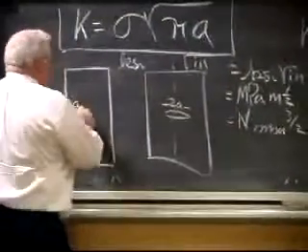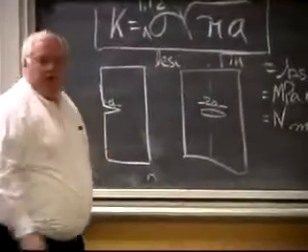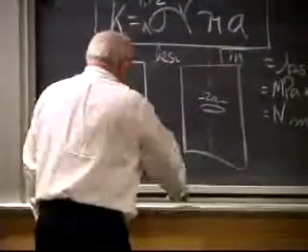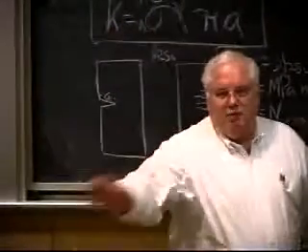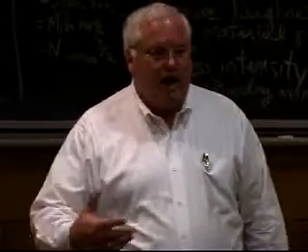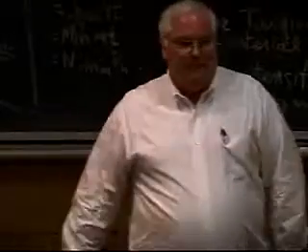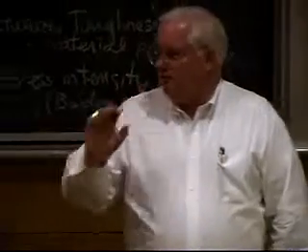times the square root of pi a. If you're talking about a pure edge crack in plane strain, there's actually a factor of 1.12 in front. And then other people divide the whole equation by Q to allow for other variations and all kinds of things. Make a whole course to complicate a simple concept, make it unintelligible. That's what academics do. Okay? Take something simple and make it so complex you don't understand it.